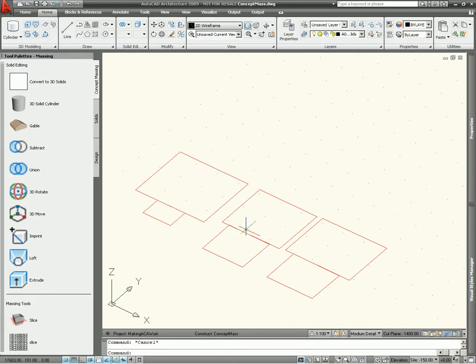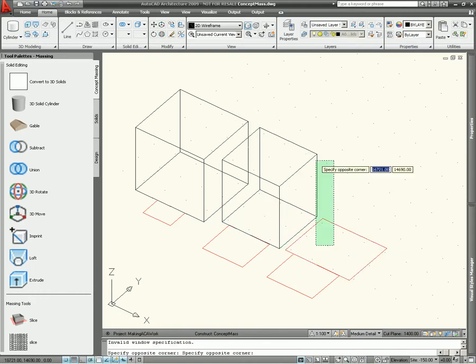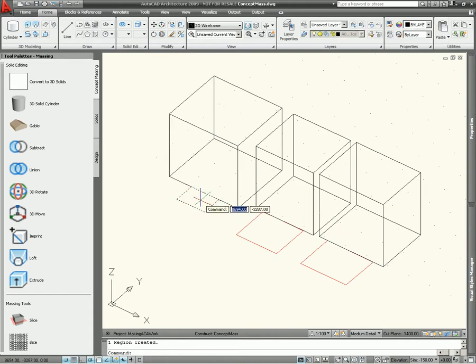Alternatively, where I've got line work, I can use AutoCAD push-pull facilities, where I'm just using the Control and Alt keys, select inside the line work, and then I can type in the height I want for that particular shape. So I'm just using Control Alt, clicking inside the line work and dragging up, and clicking on an endpoint to get the height of that shape.